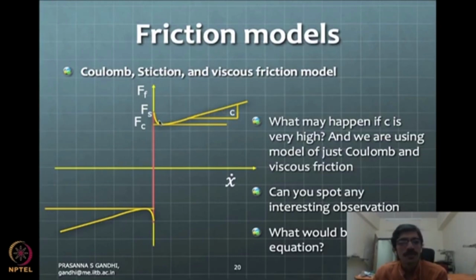In some systems, like metal to metal contact, this may not be the key situation. These are situations like we talked about in general for the entire model of friction. Some phenomena may be dominant in some cases, and some may not be, so we need to consider that appropriately. For example, in your system this friction and Fc will be there, but this change may not be so gradual.